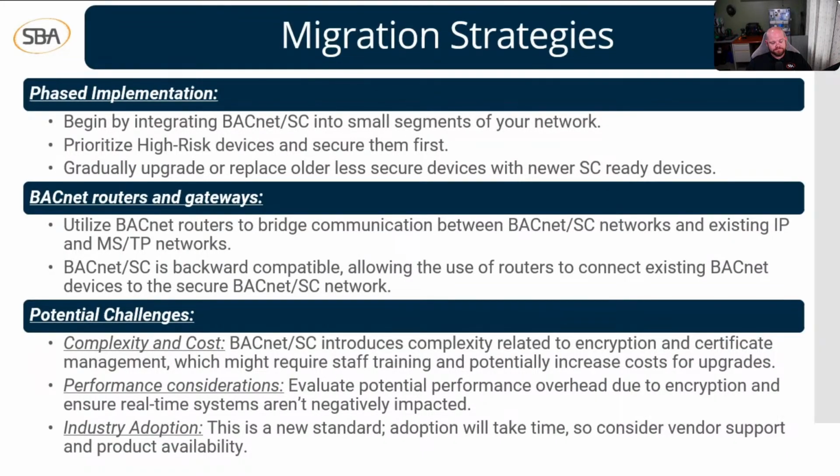Start with 5 or 10 controllers and then do another 5 or 10 later. And with that initial 5 or 10 that you do, make sure you understand how they operate, make sure that they work well, make sure you're confident with what you're looking at, and then move on to the next 5. And as you go on, you'll become more knowledgeable with BACnet SC and the controllers, and it should get easier for you as you continually upgrade.